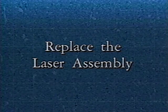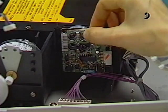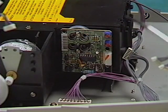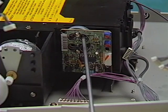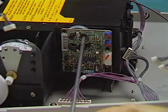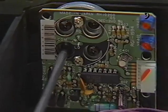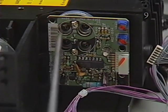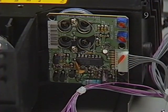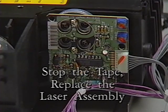Replace the laser assembly. Begin by placing the laser assembly into position. Replace the 2 black screws that secure the laser assembly to the internal printer chassis. Then reconnect connector J401 to the laser assembly PCB. Stop the tape and replace the laser assembly.